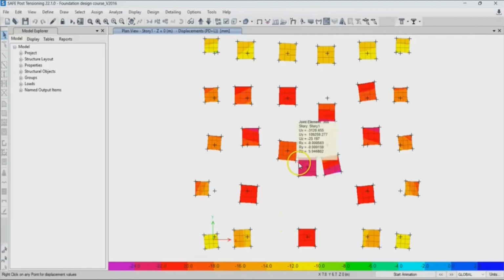So obviously, your heavily loaded column at the middle of your grid will naturally gauge deeper into the soil than your lightly loaded column. And if they are given similar size, then you might experience differential settlement. Okay, so to fix this.